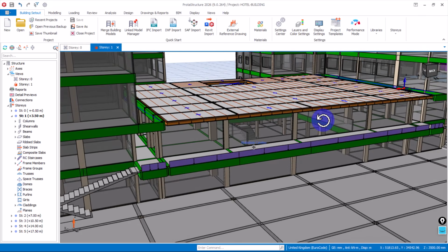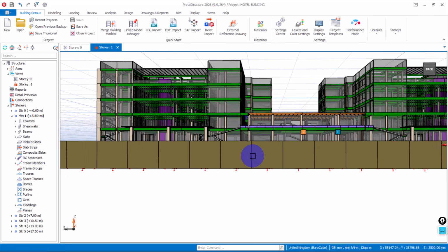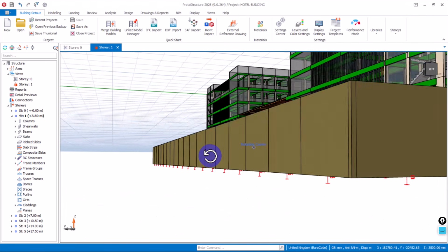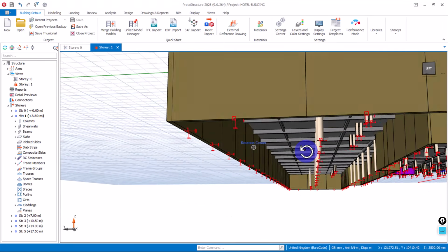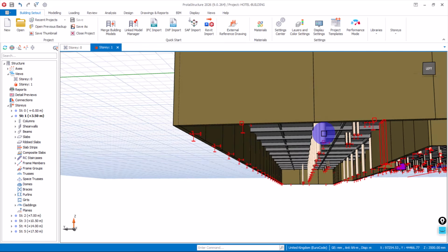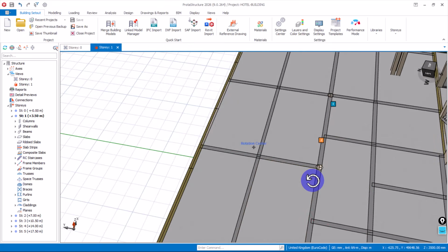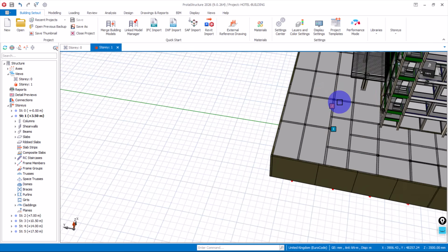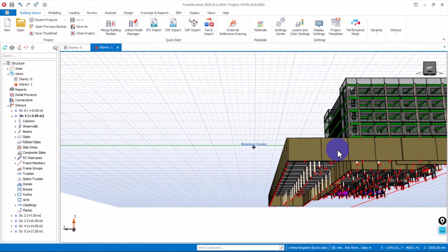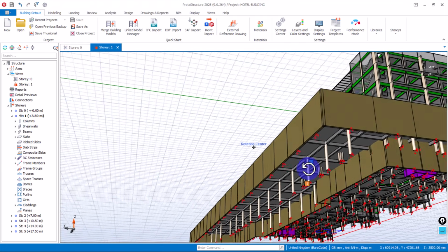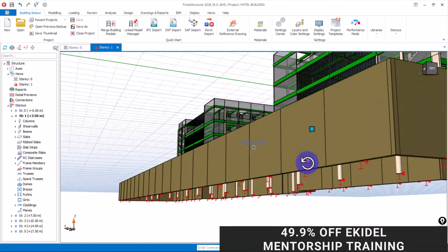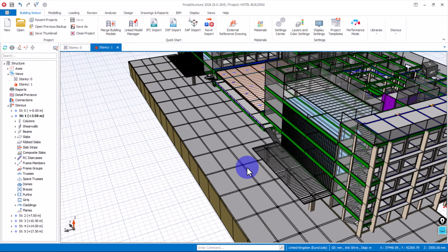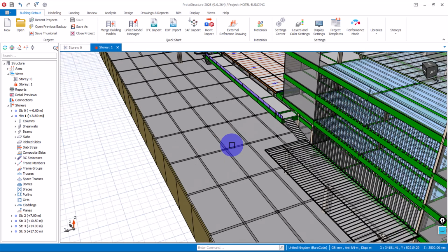which we have also modeled. Then for the car park, this basement is to be used for a car park. As you can see how we have arranged the columns, just circular columns at the middle, spanning 8 meters to 8 meters to 8 meters. Each of these basements has parking lots underneath. And at the top of this basement there is a slab which is to be used to drop off customers of this hotel building.